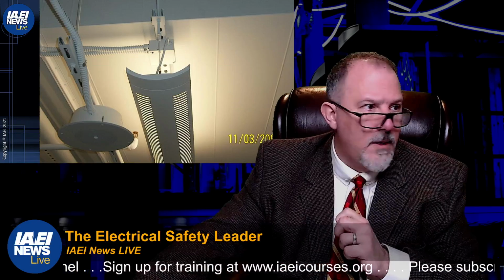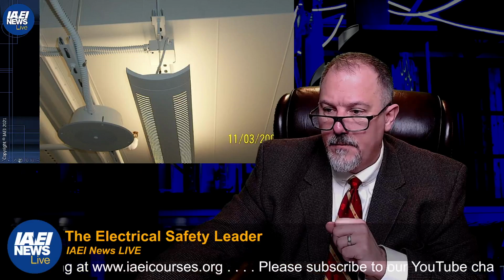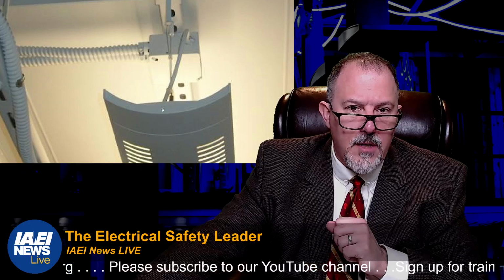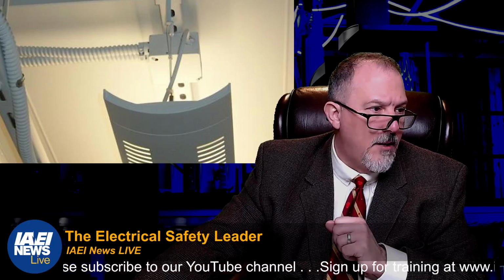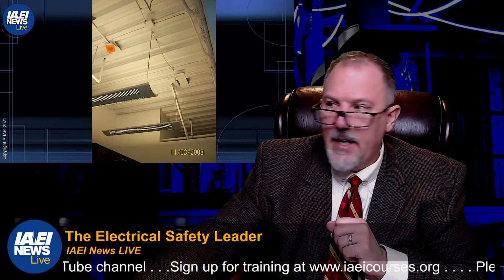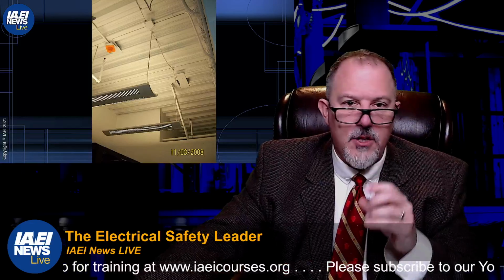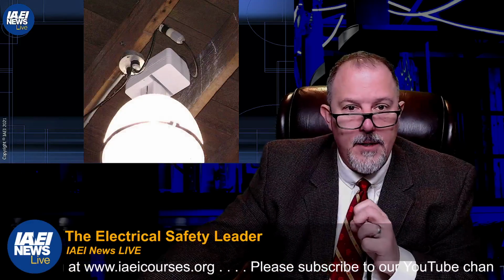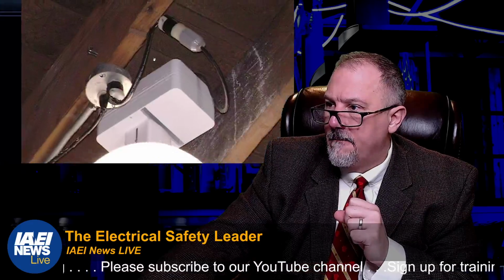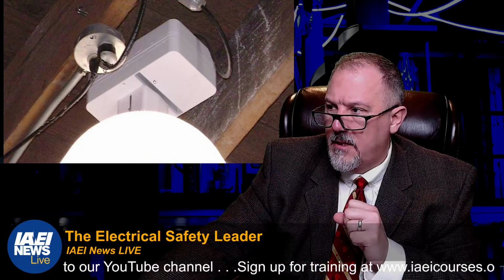So here are just some images, right? There's a flexible cord going to that luminaire right up here at the top. You'll notice there's a strain relief right in here. That's holding this, and the cord does not have tension on it whatsoever. There's your examples again. Right now, the cord is on that strain relief, so the cord is not holding the luminaire up. This is mounted. This one here is a cord plug connected, but this fixture is actually mounted to the ceiling.